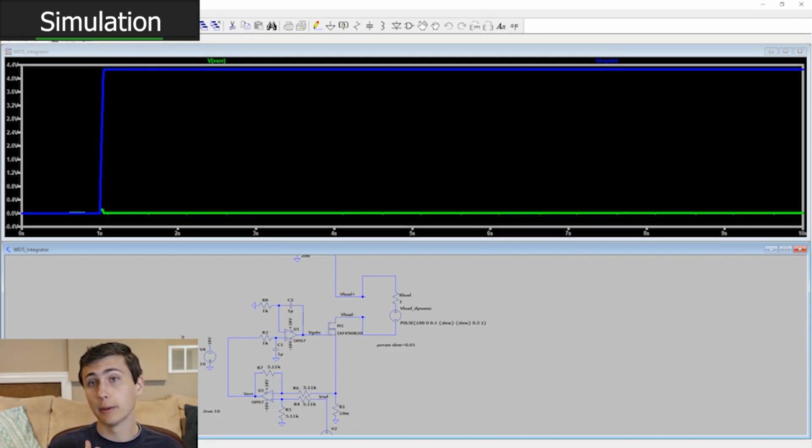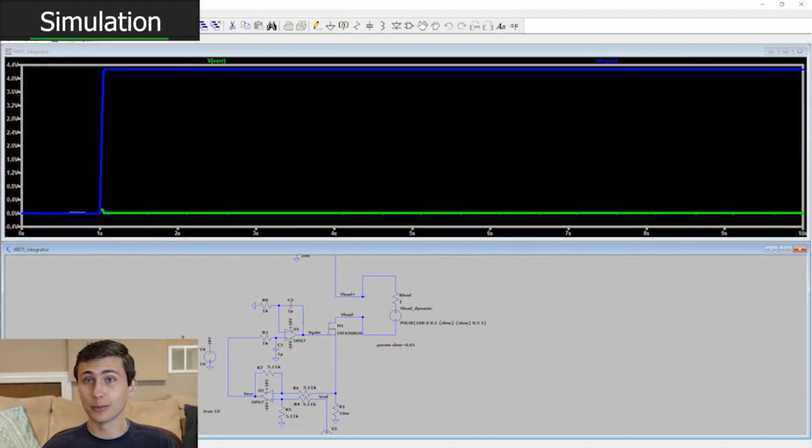So if you're thinking about this like control theory, like PID control loops, proportional, integral, derivative control, where you take those three and then you sum the combination and drive that to your MOSFET gate. This is just an integrator. Okay, this is a very simple controller, and we're going to make some iterative improvements in a future video,